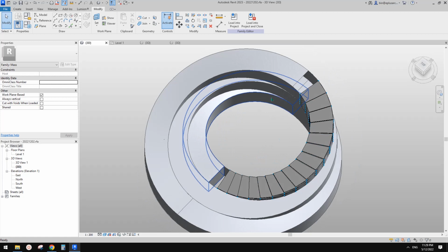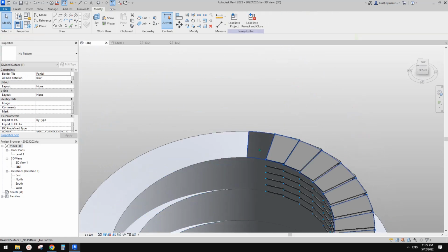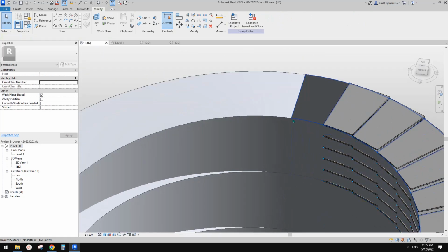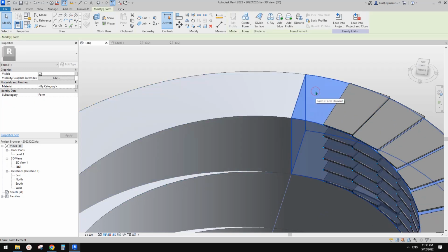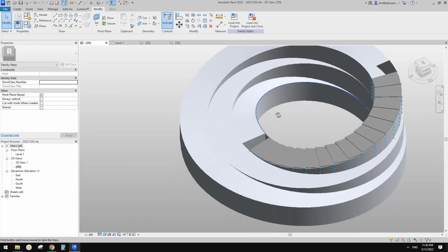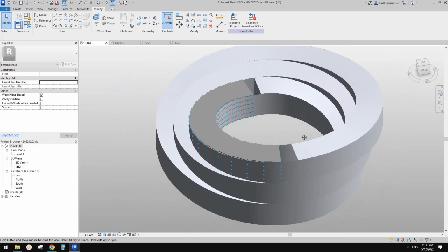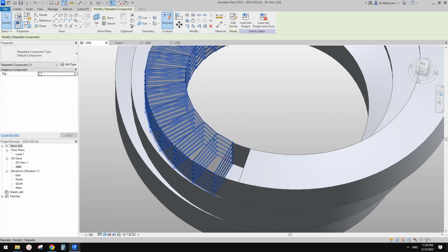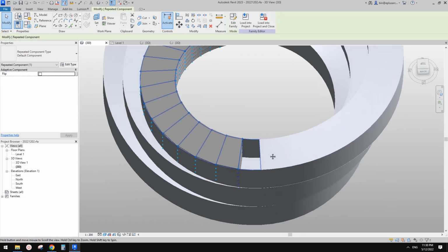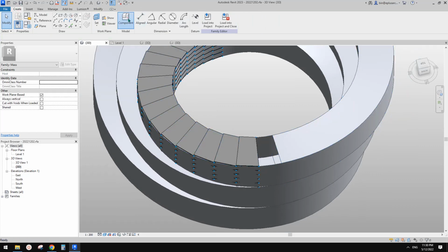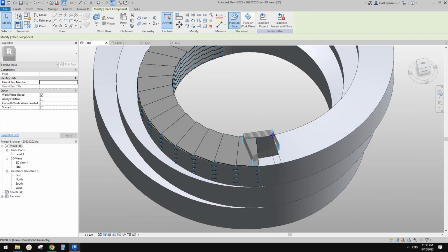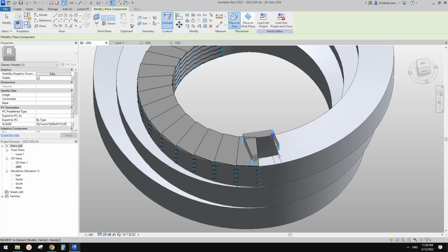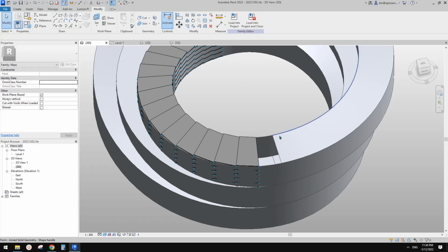Okay, it looks like it's still not perfect. You can see there's a gap here. Looks like Revit won't place because there's no nodes here. Not sure how to fix this one. Maybe we can just place manually, so I'm not sure if maybe I could go here, create a new one. So maybe we can just place manually, so 1 2 3 4 5, just to do it now here.